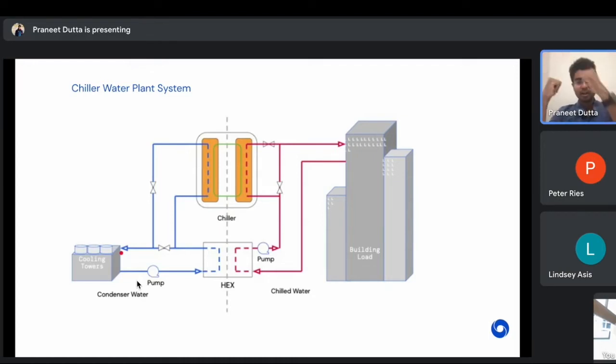Now this cooler water returns back to this central chiller area, and then the cycle repeats, where cold water comes in here, absorbs heat from here, and then goes back here. And on this loop, same thing. Warm water comes in here, it gets cooled down, goes to the building, absorbs our heat, and this entire cycle continues.